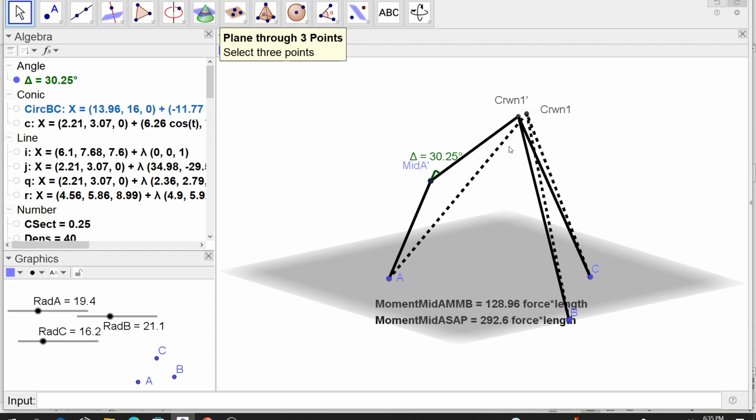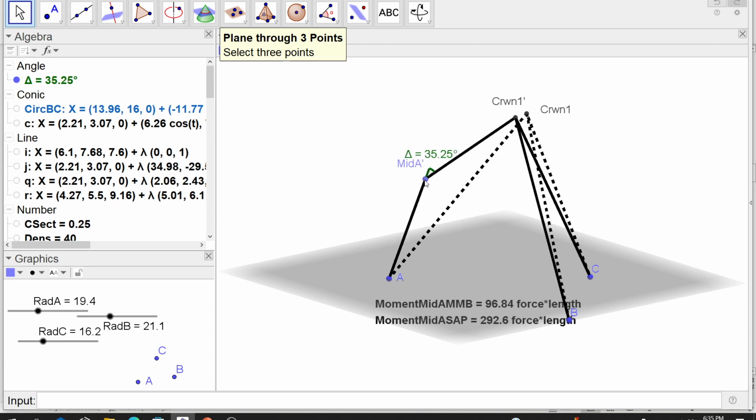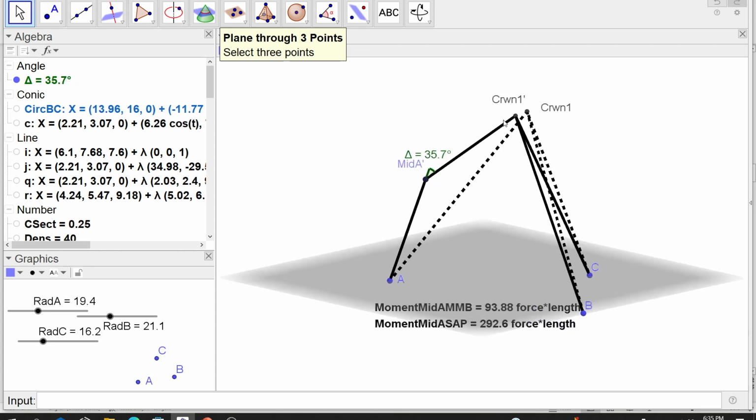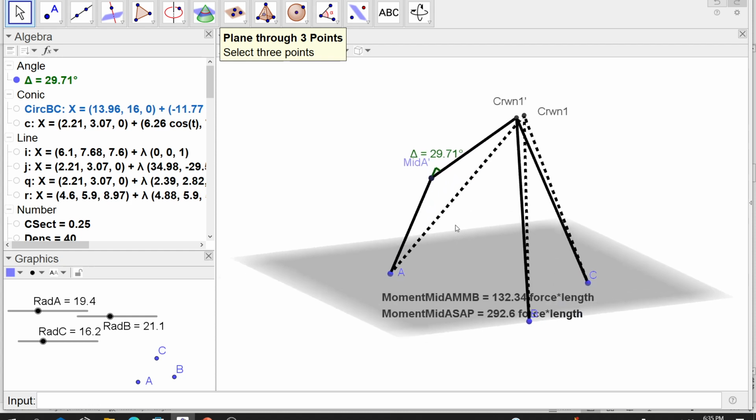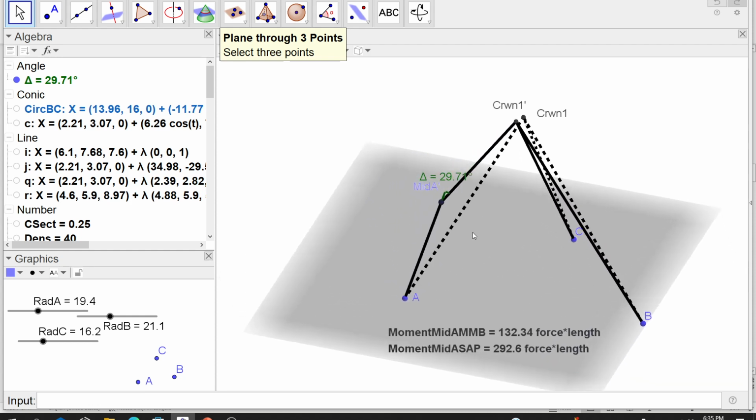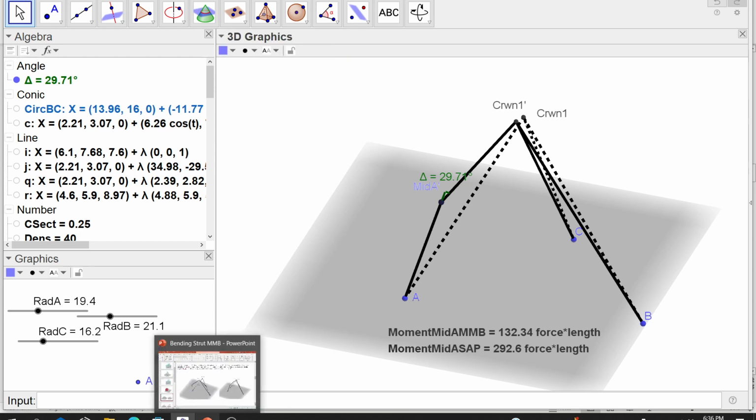It's a great lesson. But this is a secondary effect, a second order effect. It's a P delta effect, what we call in nonlinear mechanics. So it's the force at the eccentricity from this line to the cut. That's so cool. But of course, the second order effect disappears for very, very small perturbations. And for large perturbations, it's there. It's a great visual tool. I don't think anybody's done this, but you can explore it.